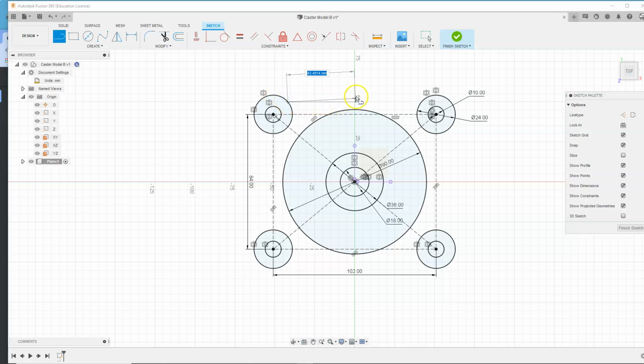Left click to place the line. And it's going to snap to kind of horizontal. I want that for sure. And it's going to snap to the other circle. So that's my nice horizontal line. That symbol right there means horizontal. But I want this to be at the top of the circle.